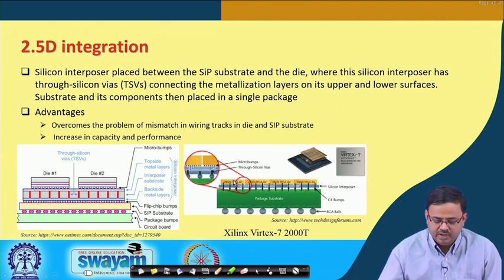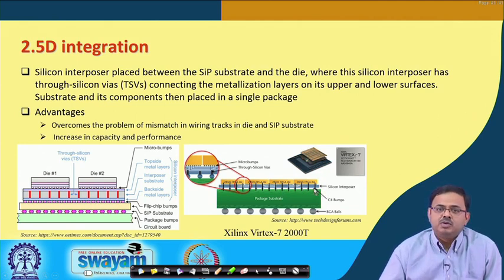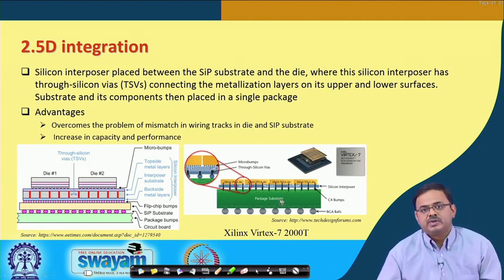So, you see here you have 4 of these FPGA flip chip dies. Okay, it is flipped, and then you have a silicon interposer, and then you have these C4 bumps, which we saw in flip chip, controlled collapse chip connect, if you recall, C4. And then you have the package substrate, and then the BGA balls.